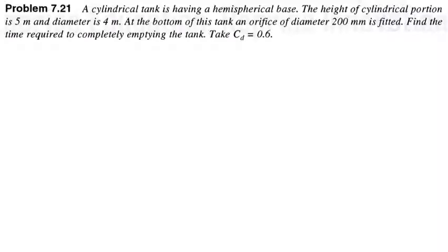Now let's see a problem. A cylindrical tank is having a hemispherical base. The height of the cylindrical portion is 5 meters and the diameter is 4 meters. At the bottom of this tank, an orifice of diameter 200 mm is fitted. Find the time required to completely empty the tank. Take coefficient of discharge as 0.6.